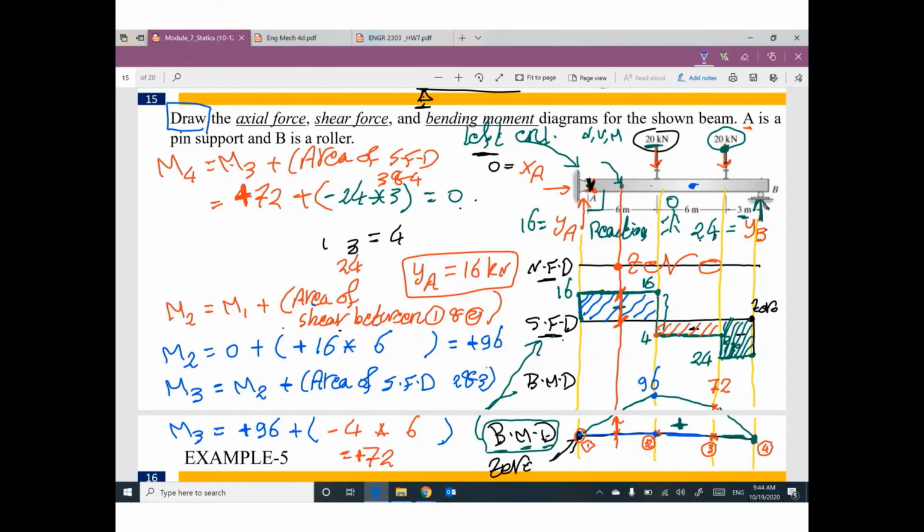Yes, I can tell you. Go down at this point in these diagrams. Your normal will be 0. Your shear will be -4. Your moment will be this value. So drawing diagrams will give you any value at any specific point inside this beam.